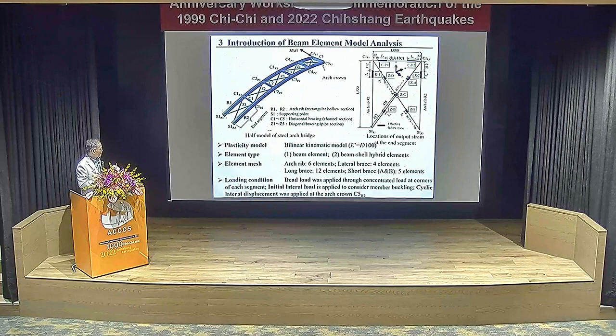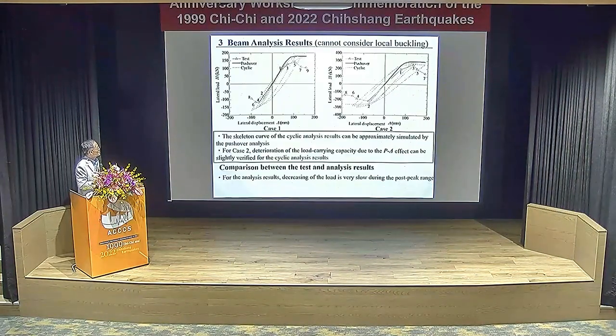And then we perform the analysis, using the dead load and also putting in the initial lateral load to consider member buckling, and finally putting the lateral displacement here. We perform two analyses, pushover and then cyclic analysis.